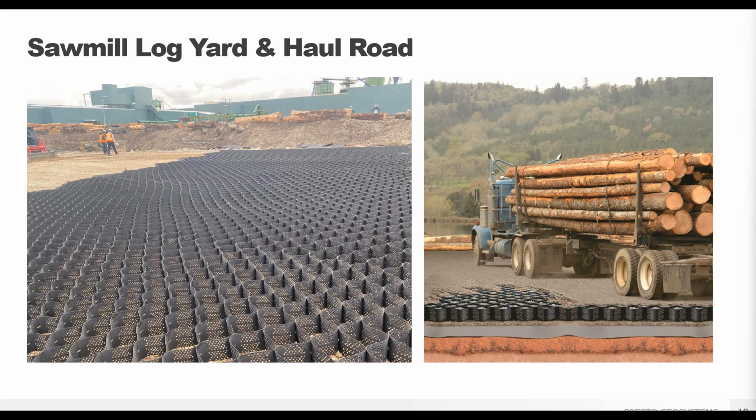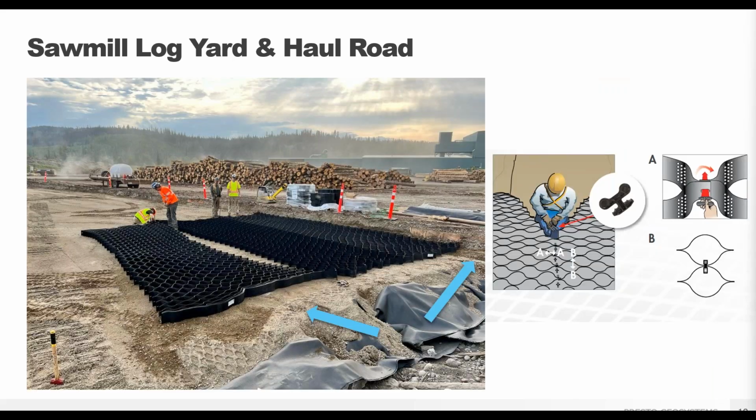Presto worked with the owners to develop a design to manage stormwater and snowmelt while providing stabilization and support of the heavy loads over soft subgrades. A 6-inch or 15-centimeter GeoWeb load support system with high-strength woven geotextiles was installed with infill designed to promote stormwater infiltration.